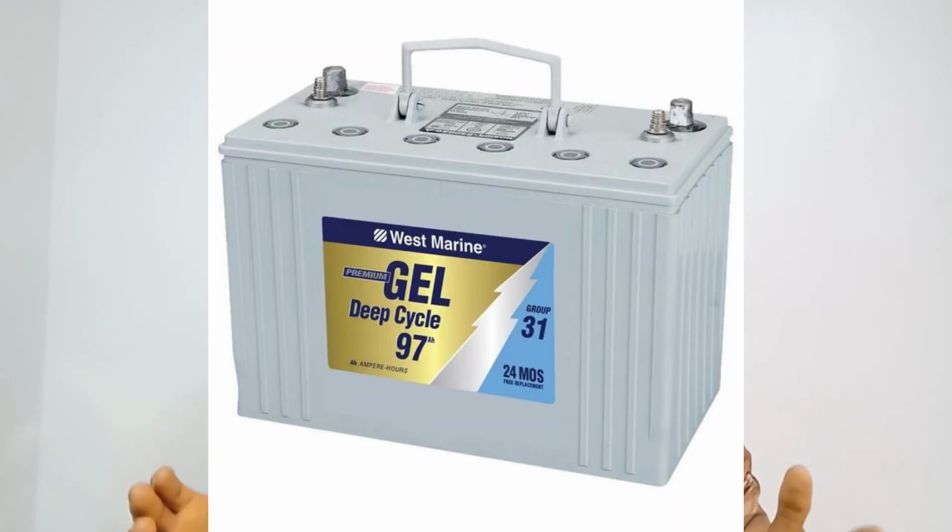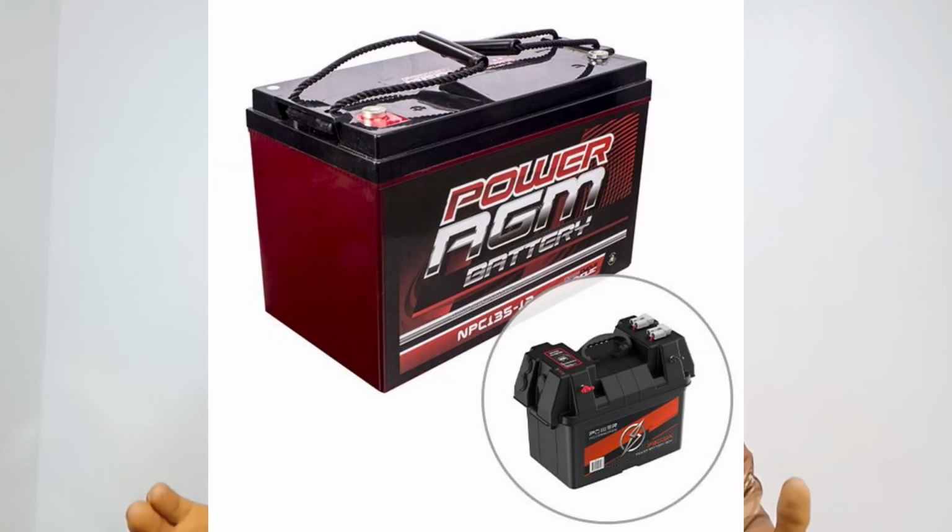We have another type of lead acid battery, which are the gel and the AGM battery. The gel and the AGM batteries are the maintenance-free lead acid batteries. They don't require any maintenance. The gel and the AGM batteries have a shorter lifespan compared to well-maintained flooded lead acid batteries. They also cannot handle high charge and discharge rates, unlike the flooded lead acid battery.